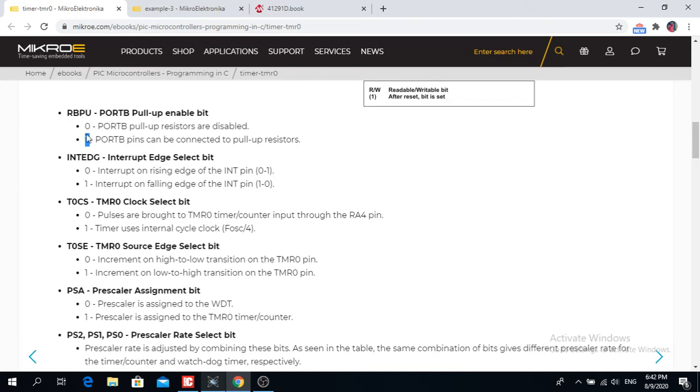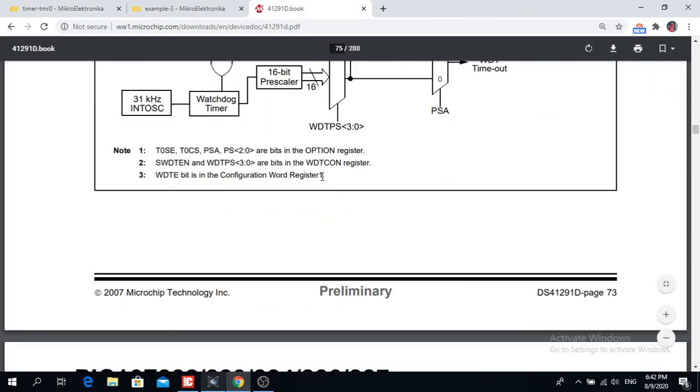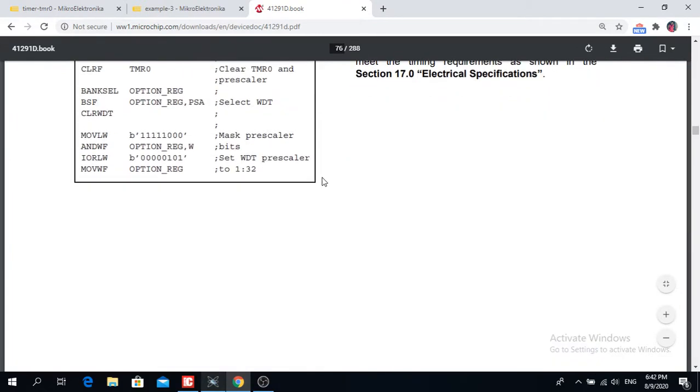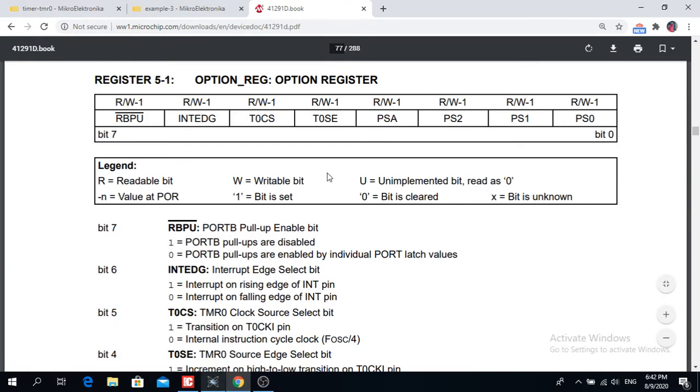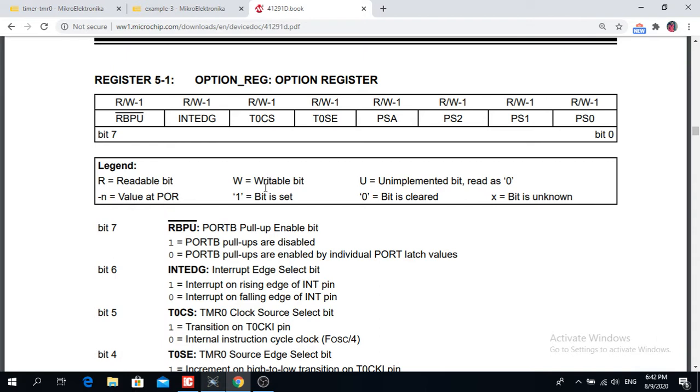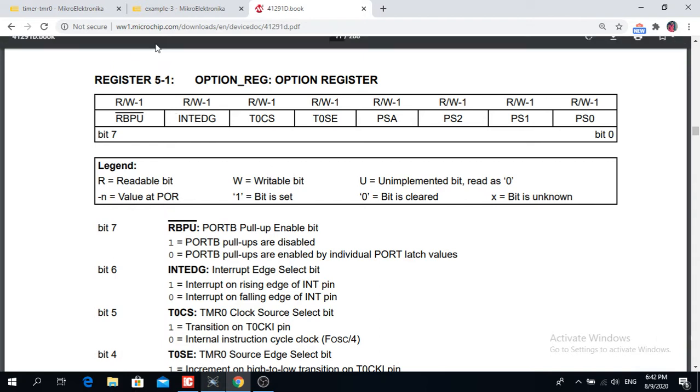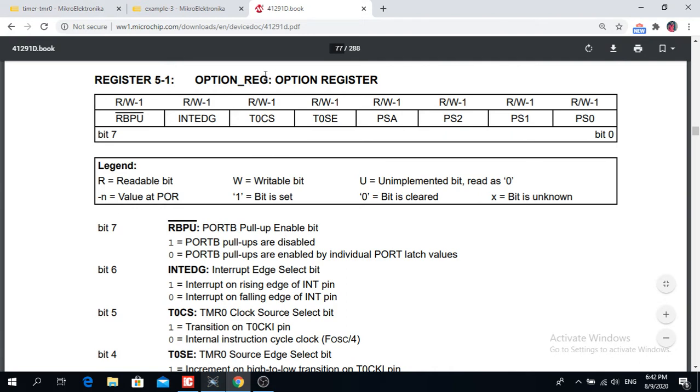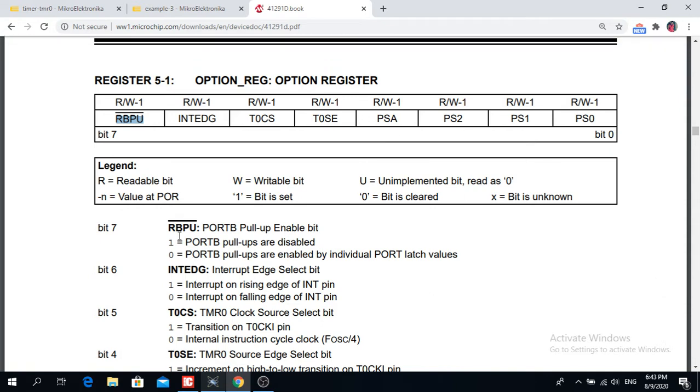From this here it is 0 1 1 0 1 0 and to PSA. I saw that in the data sheet of this particular PIC microcontroller. So yeah, it isn't important. We can also look at this special function register in the data sheet of this microcontroller. So if you bring 0 or 1 here, it isn't important for us in this particular program. We don't even use port B, so nothing to see here.